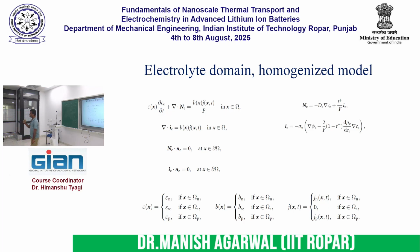So now in case of homogenized, if we summarize the things, in case of lithium movement, things remain as they are, because we have not done any homogenization. For other things, there is a homogenization that has happened. What it has done is, it has converted the area terms into the source term, and these kind of source terms are appearing now in the equation.